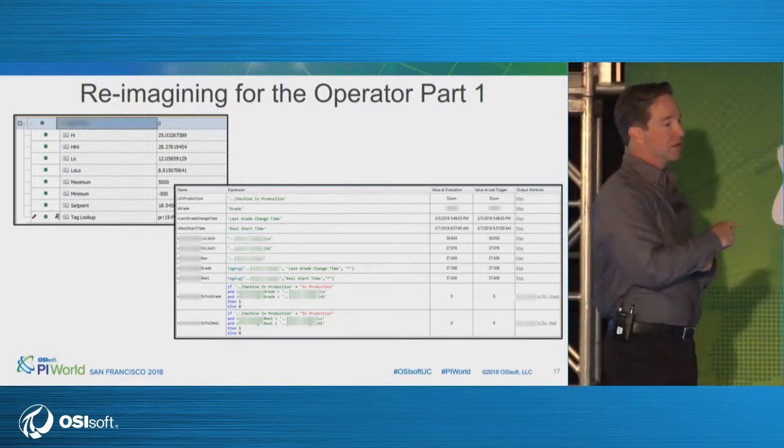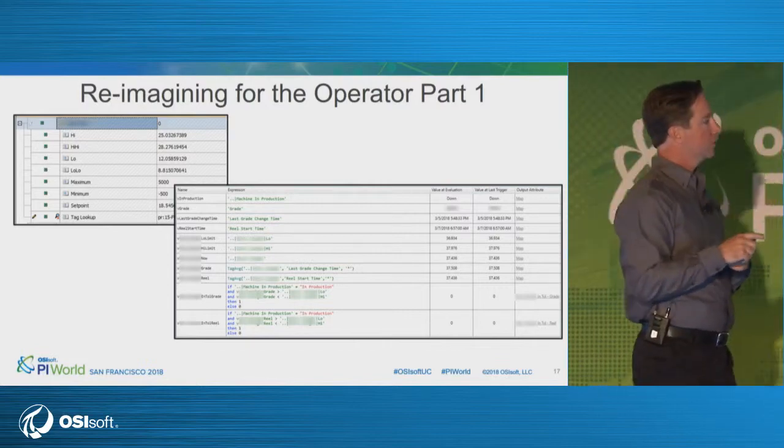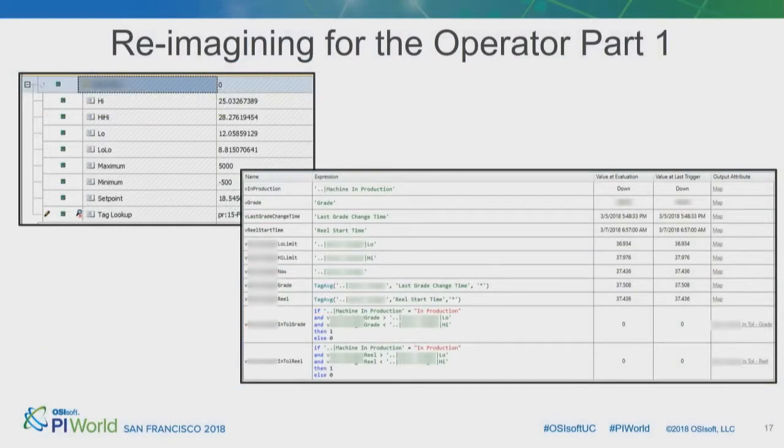So I don't know if you guys all know this. I'm sure a lot of you do. Every PI attribute can have a set of limits associated with it. It's a matter of right-clicking, and there's a little thing called limits. They introduced this, I don't know, a couple years ago. Use them. And then what we did is we tied them to a table. And then that table, you can actually type the limits in if you so choose.